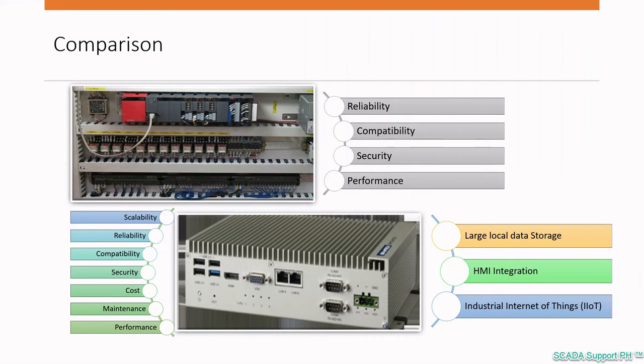If we put those two hardware types side by side and focus on their advantages, we can see that cost and scalability are very much in favor of a PC-based solution. PCs will be easier to scale than a PLC-based application, as they can easily be updated to handle more data processing by simply adding more memory or processing power.